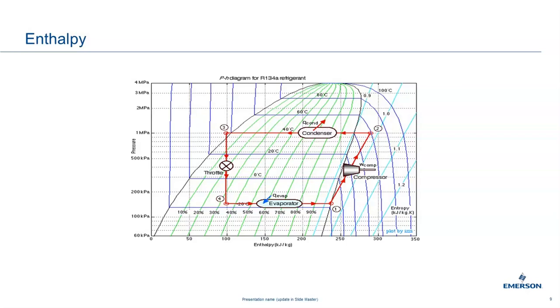And just a little side note here, if you ever look at a PT chart and it says bubble or dew point, we're looking at our dew point on the vapor side, and they're referring to the bubble point on the liquid side. And the way I look at that is, remember sub-bub, okay, and su-dew, okay? That's the way I recall it.